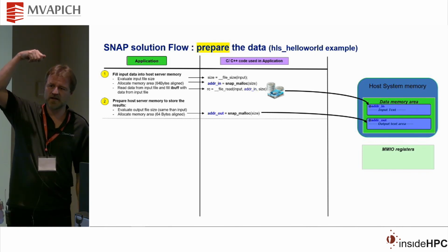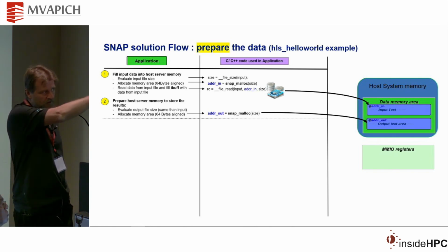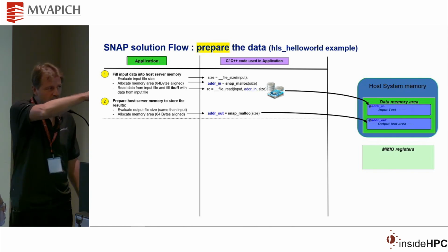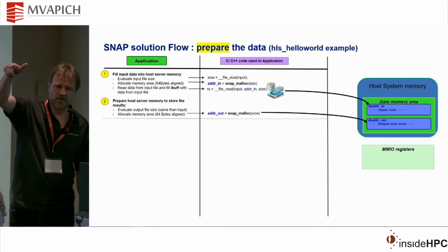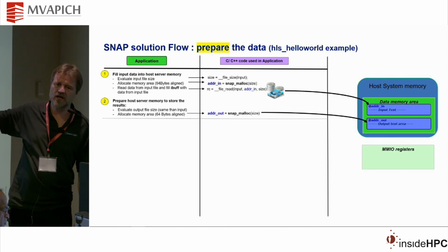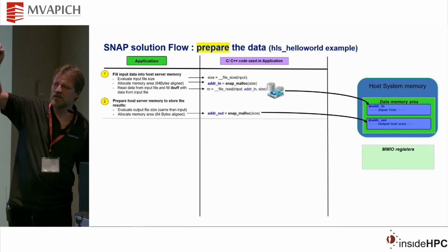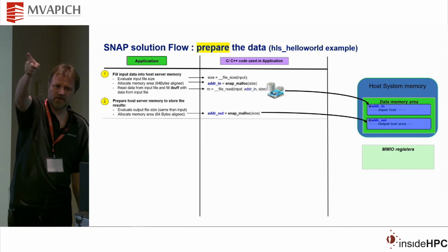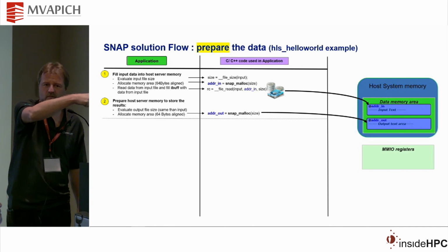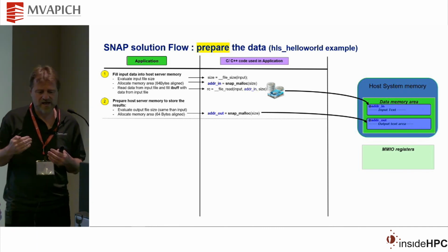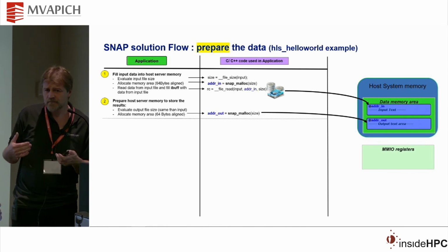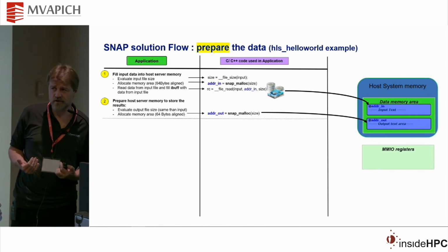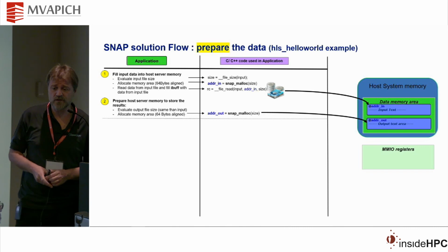I will write a flag into the memory, so I don't care about this very low bandwidth communication. I will put a flag: hey, image is ready. The CPU checks the flag. Flag is ready. Okay, GPU, your turn. You can process this image. When you're finished, I will inform the FPGA. So the CPU is really acting as an orchestrator, and a very small number of instructions are required to make the complete computation process work.